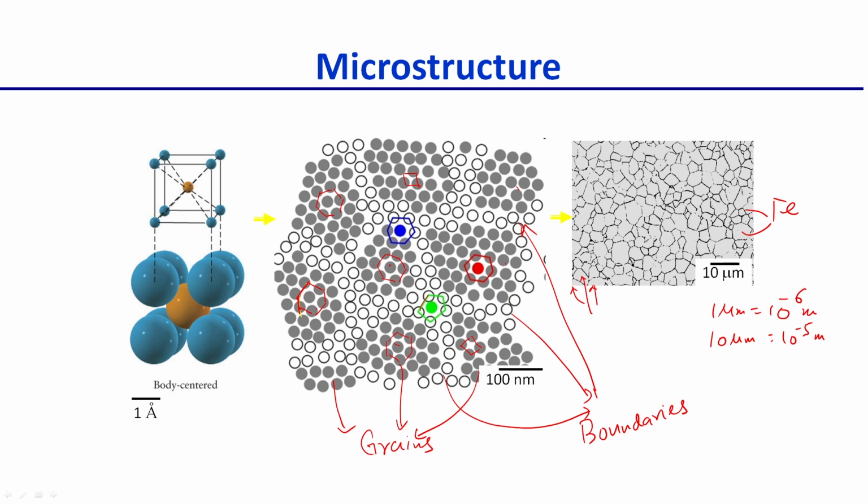So, now you can see that there are two aspects here in a normal material in the microstructures. One is the grain, where the arrangement of atoms is regular, another one is the boundary. That is why the boundary atoms are haphazardly aligned or placed. So, therefore, grain boundaries have a lot of free space present, where atoms can migrate, a lot of things can happen, okay. And this is an important area of the subject.